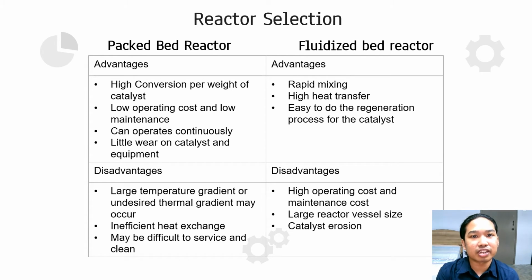While the fluidized bed reactor has rapid mixing, high heat transfer, and is also easy to do the regeneration process for the catalyst. Some of the disadvantages of the packed bed reactor are that undesirable thermal gradients may occur, inefficient heat exchange, and it may be difficult to service and clean. While for the fluidized bed, there is high operating cost and maintenance cost, large reactor vessel size, and lastly, catalyst erosion. After considering the specifications, the packed bed reactor was used for this process.